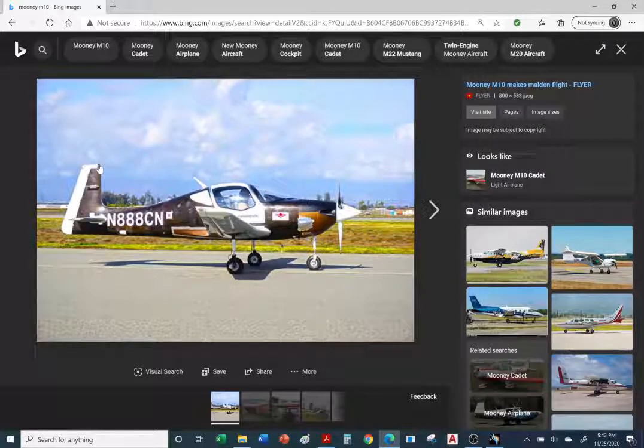So they asked me to basically start from scratch and create a new rudder and a new horizontal stabilizer, one that could be adjusted so we can find the angle of attack. Typically the horizontal stabilizer is fixed, but for this prototype, we're going to allow it to rotate slightly so we can find at which angle we can set it to be more fuel efficient, and also design a new rudder.